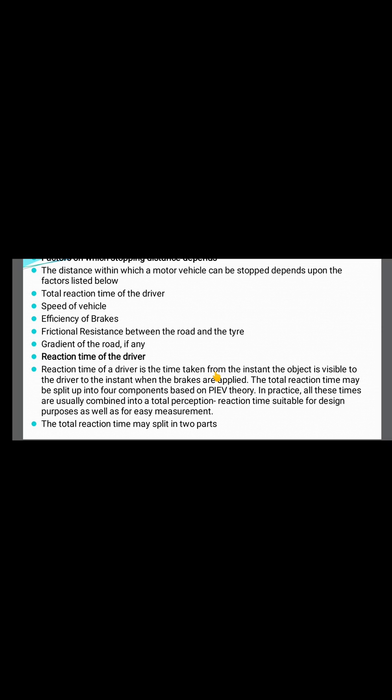So first is the reaction time of the driver. Reaction time of the driver is the time taken from the instant the object is visible to the driver to the instant when the brakes are applied. This total reaction time may be split up into four components based on the PIEV theory. In practice, all these times are usually combined into total perception and reaction time, suitable for design purposes as well as for easier measurement.